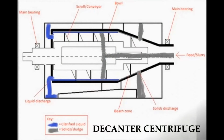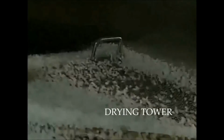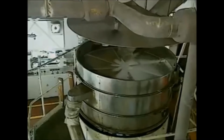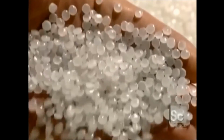The pellets are then transferred to a decanter centrifuge where most of the water is removed. They then pass through a drying tower where, after being screened by size, water and remaining ethene are removed using a stream of air. And this is the final product of polyethylene pellets.